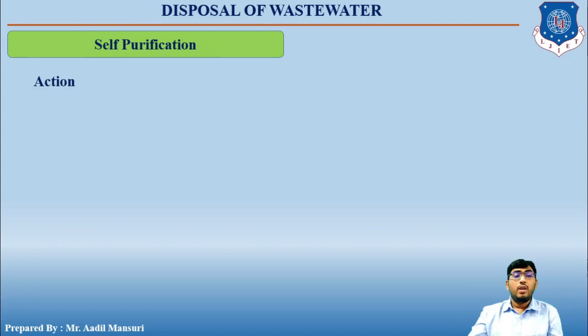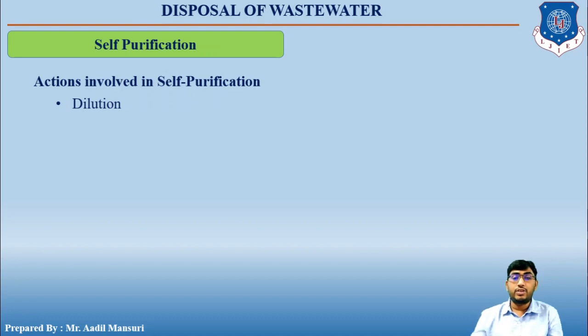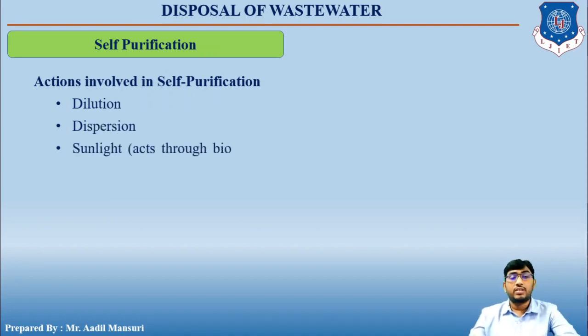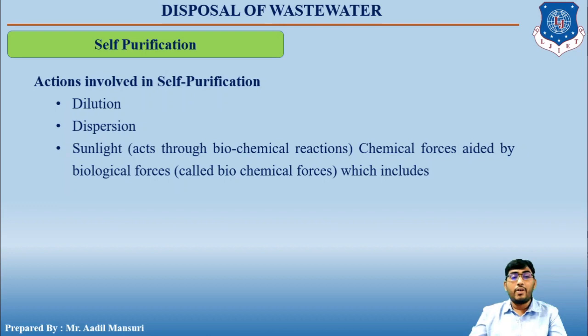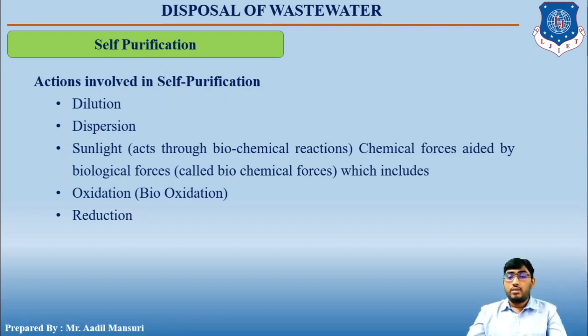So the actions which are involved in self purification include dilution, dispersion, sunlight which acts through biochemical reactions, chemical forces aided by biological factors called biochemical forces, which include oxidation, that is biooxidation, and reduction. This automatic purification of polluted water in due course of time is called self-purification.